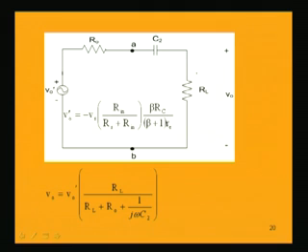Now, in this circuit we can find out what is V naught at this point. So, V naught equals the voltage across these 2 points, which has the resistance RL. So, V naught equals V naught dash into RL divided by RL plus this series resistance and capacitance.